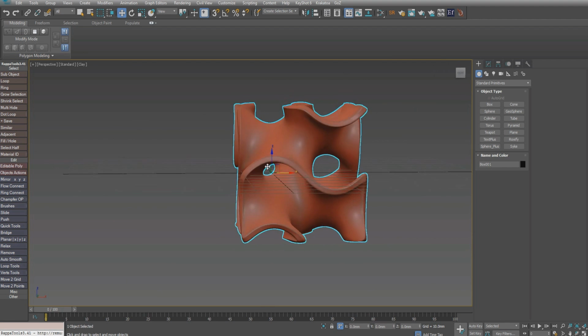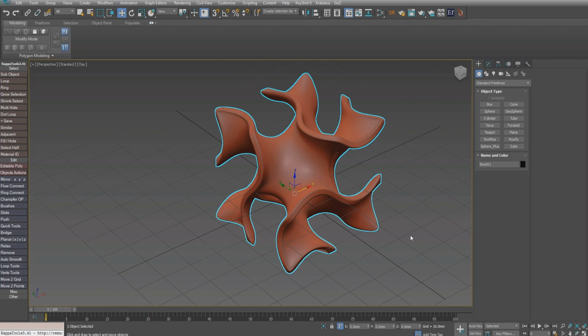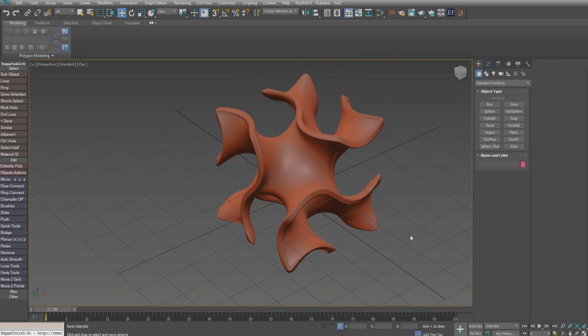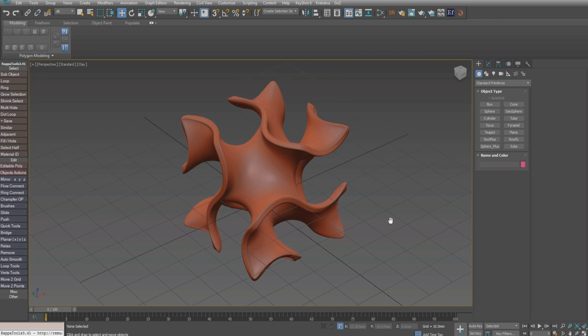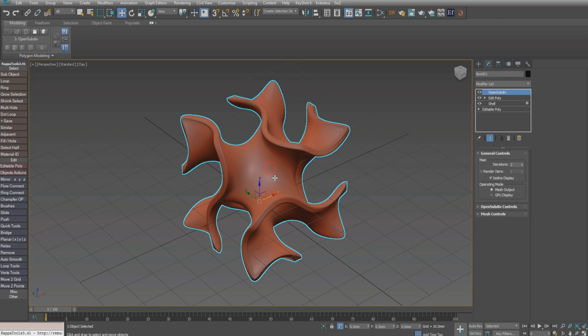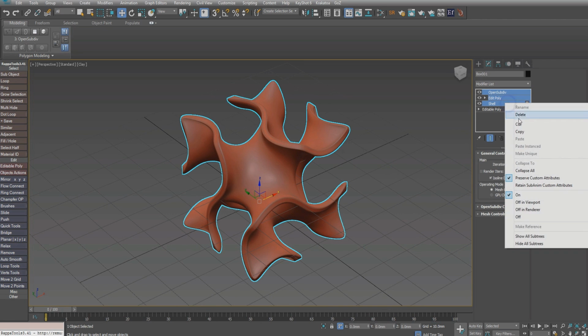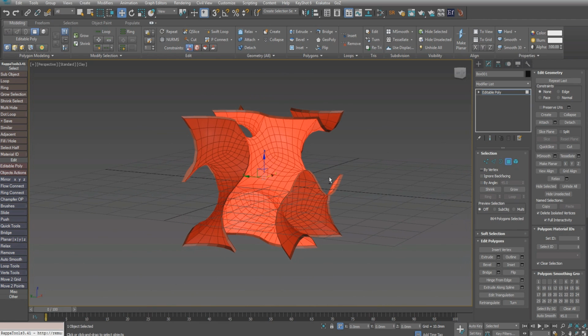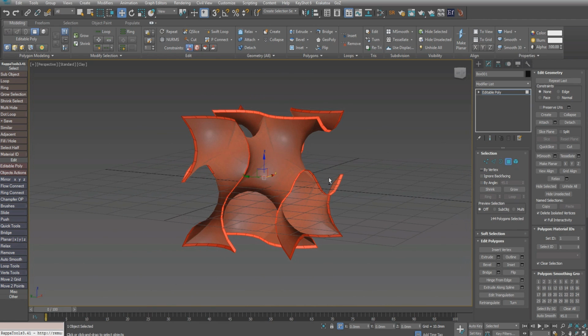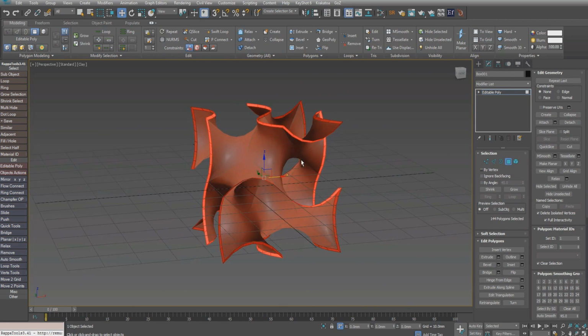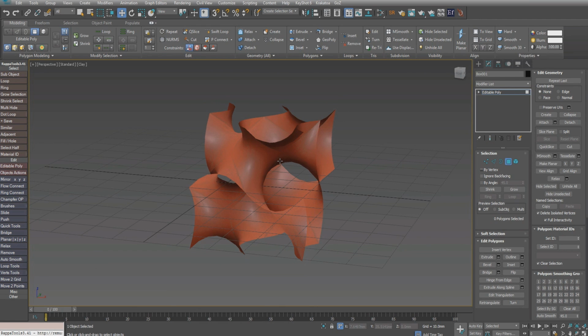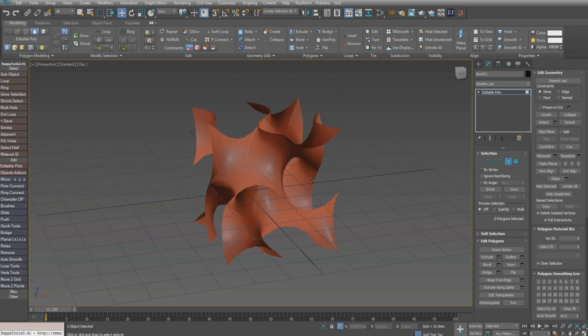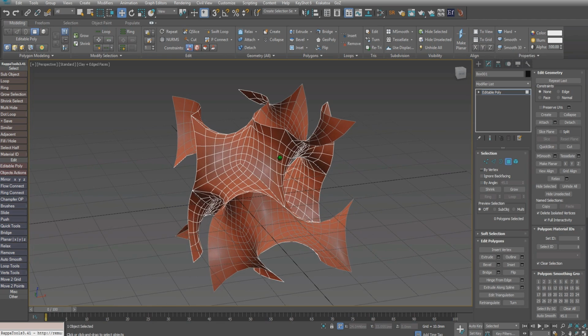If we did want to create a triply periodic gyroid, this is only an element of a triply periodic gyroid. It's just one section, really, and I can show you what I mean here, but what I'll have to do first is remove the modifiers we currently have, go back to just the editable poly surface, not manifold, and the edges that we created from the border, I'm going to remove those just by deleting them.